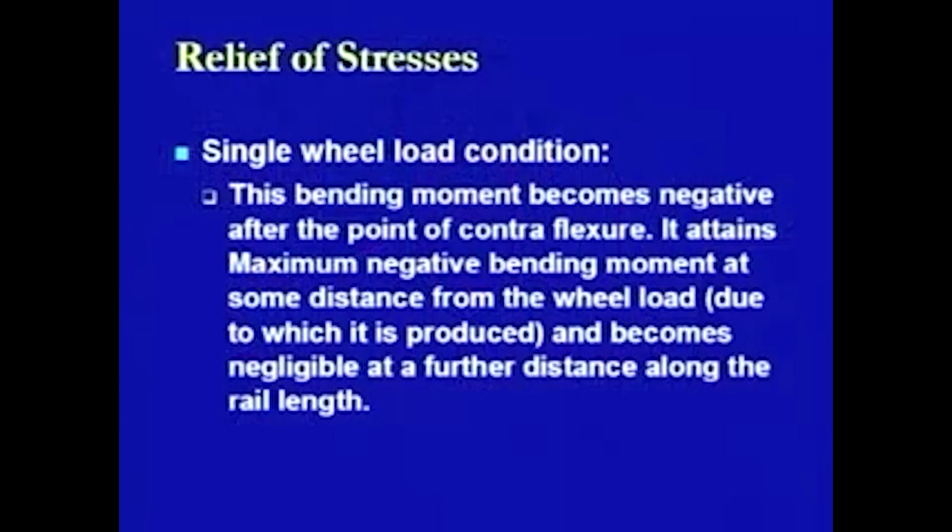Now, this bending moment becomes negative after the point of contraflexion. So, it depends on what sign notation we have used. If we are using the positive bending moment just below the load being applied, then after the point of contraflexion it is going to change its sign. So, if that is positive it will be negative, or if that is negative then this will be positive.